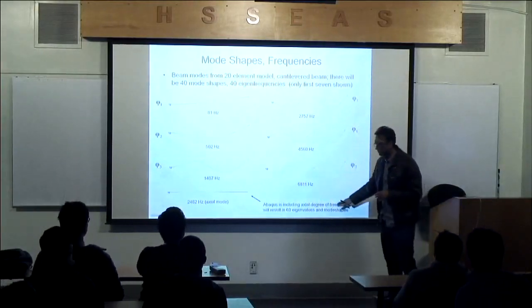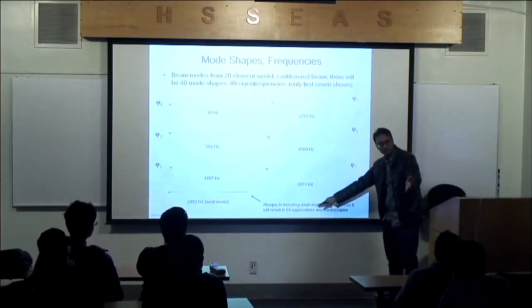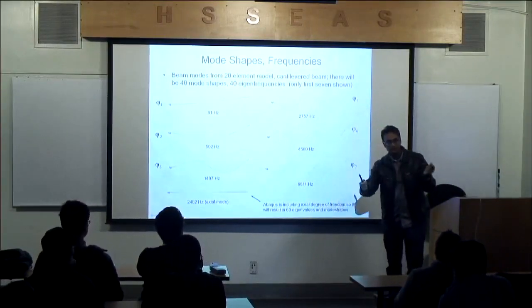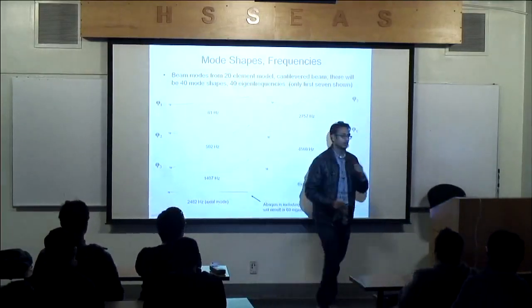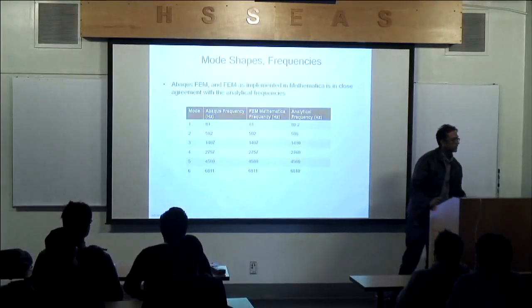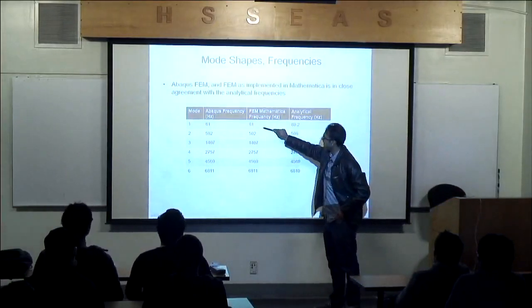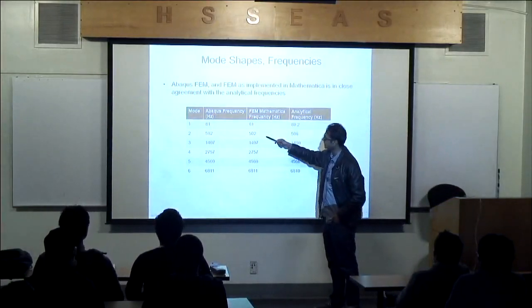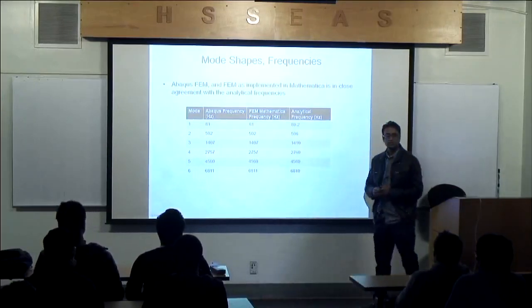I put the note here on your question: 60 eigenvalues, 60 mode shapes, 60 of them because of the axial flexibility. But if we ignore those, we should really have 40 of them. Now, how does that compare to what I got with Mathematica? Look at that. That's Abaqus, that's us, 5 elements. And it's matching 1 to 1. I expect that, it should match.